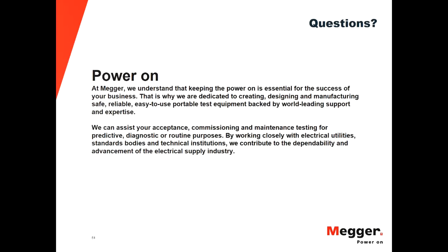Related to capacity testing, the test will be the same as we just described in the general concept. We want to discharge the battery down to a minimum voltage and check if it is giving us the capacity that is on the nameplate, or how that capacity is degrading.